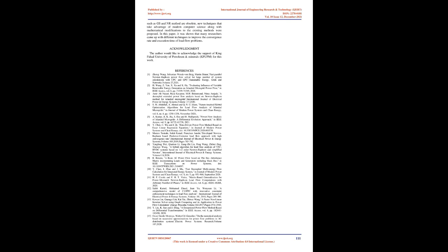The proposed method was implemented on 10-bus, 33-bus, and 69-bus test systems. The proposed method was compared with multiple PF techniques such as NR, GS, LM, and BF. It was shown that the execution time for load flow analysis using successive approximation is the least among the tested techniques.